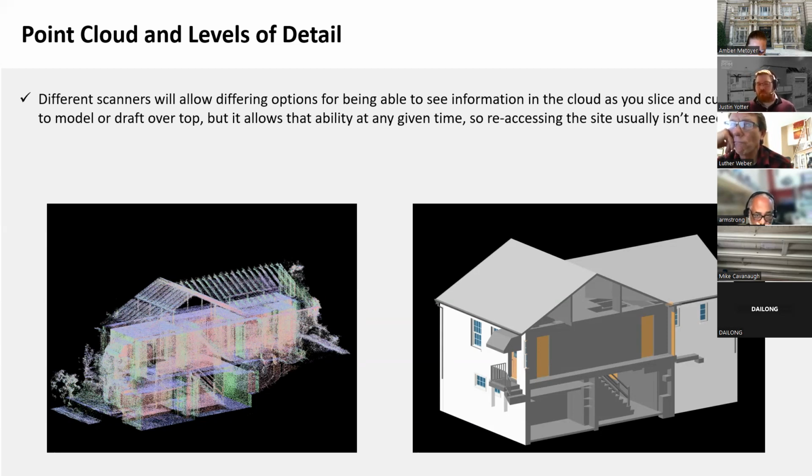So let's see. What does that mean? While we take verifying measurements, we know the bones of the scan and the model and drawings will be accurate, yet there can be variations based on angled or skewed walls, assumptions on interior wall accuracy versus global accuracy, etc. And so knowing what is most important in your scope and standards may help the third-party drafter, surveyor, or even your internal staff keep those judgment calls aligned with yours.